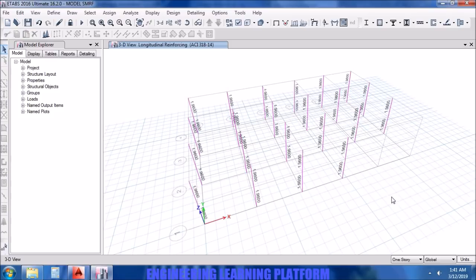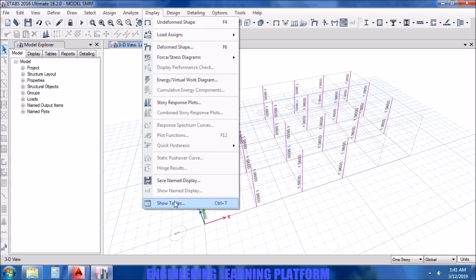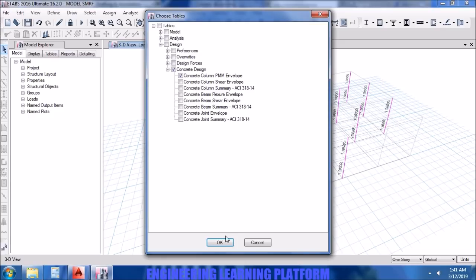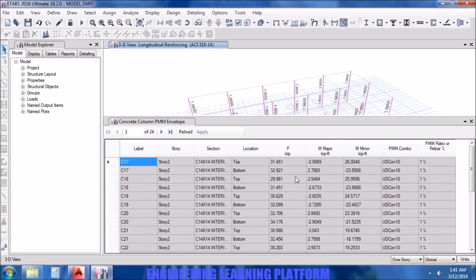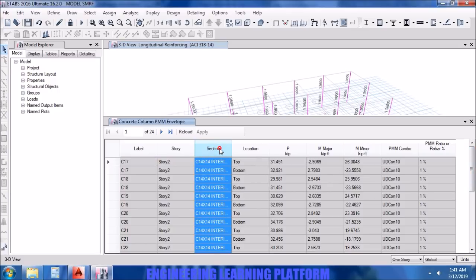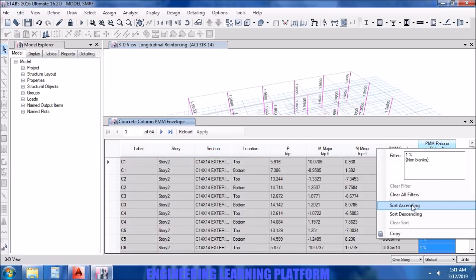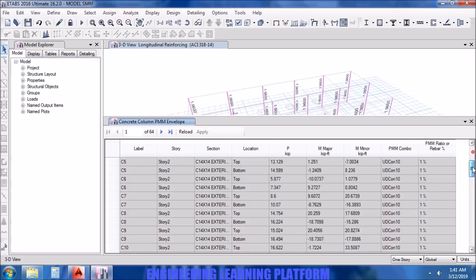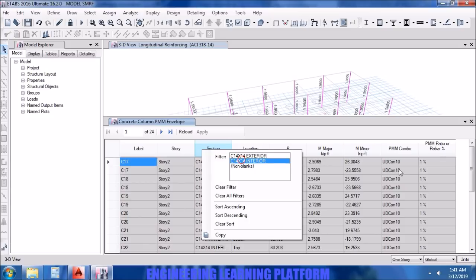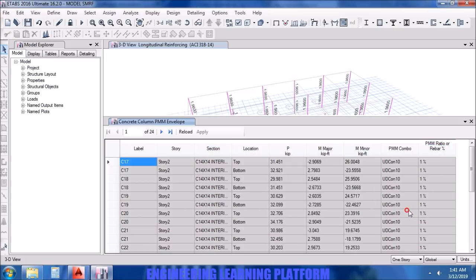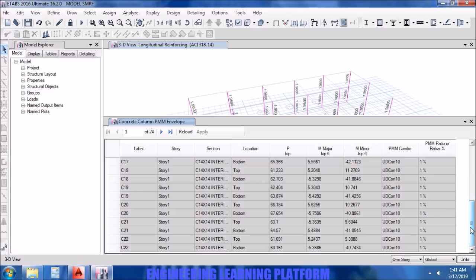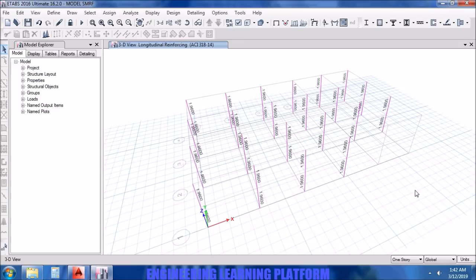The next thing we will be doing is checking the stability. Let's check the column rebar percentage first. The rebar percentage is within the limit of maximum 8%, which is totally okay. So the size of the column is adequate up till now for the checks which we have applied. All column steel is at the minimum, that is 1%.